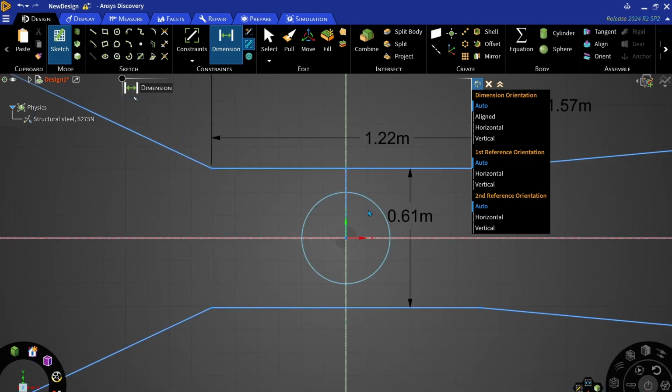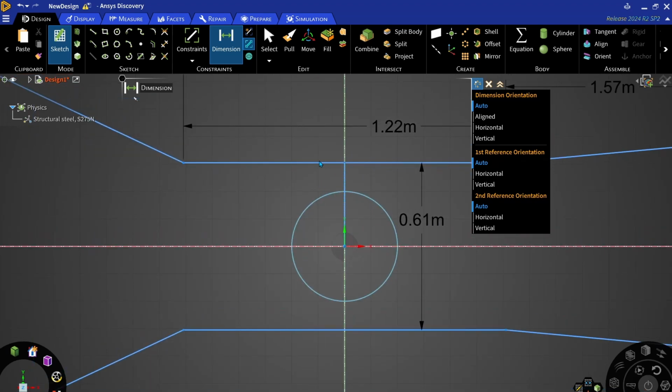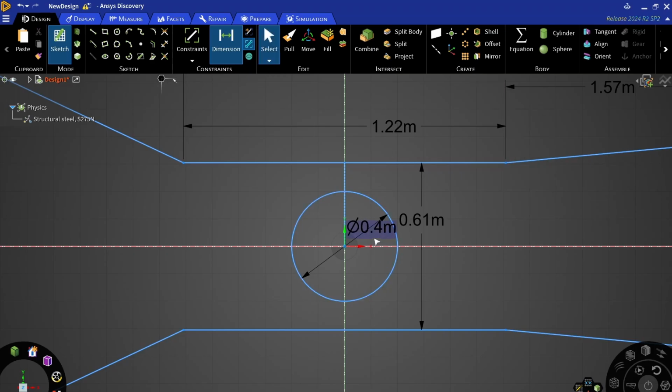This is so the walls of the wind tunnel don't affect our results, because if it's too big, you're going to have a lot of air going really fast in here because of Bernoulli's principle, and the air around here is going to be a lot faster, and it's going to affect your results. So we're going to dimension this.